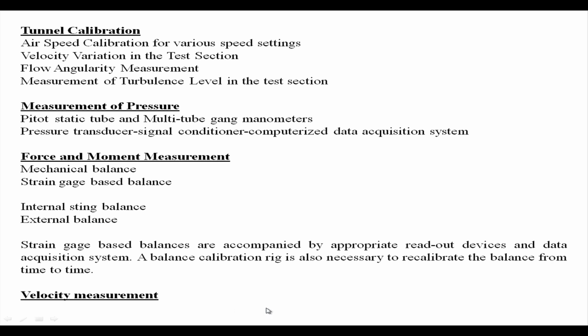And of course, the strain gauge based balances, just like the pressure transducer systems here, have to be accompanied by appropriate readout devices, DACs, and of course interface with the computer. And also additionally, you need to calibrate all these devices from time to time.